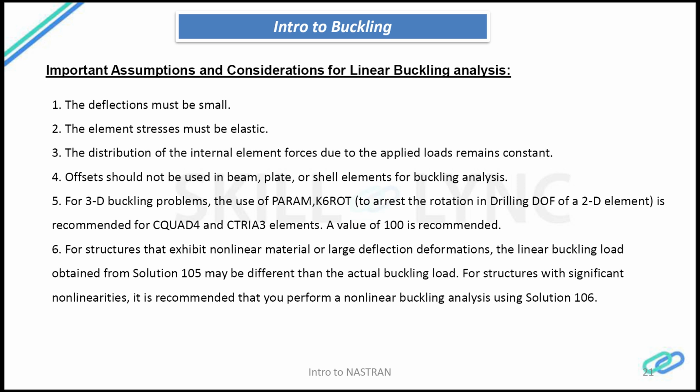Point number 4 and point number 5 are limitations of the tool, which is Patran and Nastran. One thing is, while you are carrying out buckling analysis, if you have beam elements or plate elements or any elements where you have specified an offset value in the property cards, you should make it 0, or remove it.